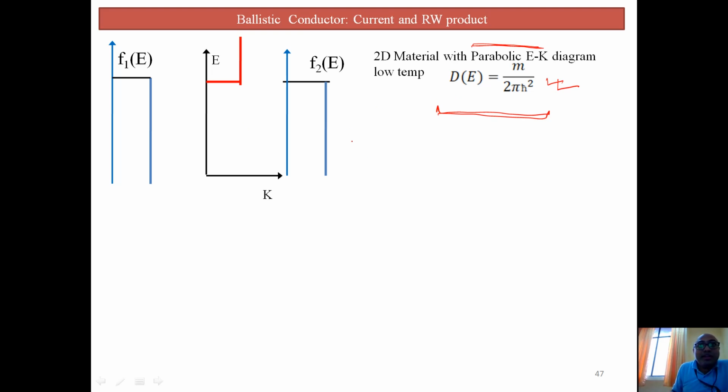This case is called equilibrium. So suppose it is in equilibrium. In this case, this is the number of carriers, meaning the number of electrons. It is the usual formula: the integral of dE, density of states multiplied by the Fermi-Dirac probability.